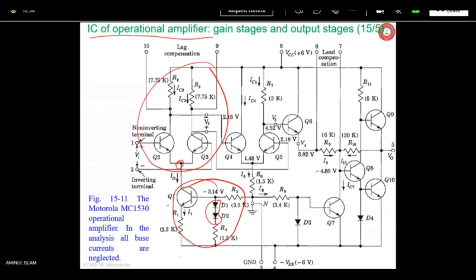Okay, so both are the same, I mean Q5 and Q4, so both VEN4 and VEN5 will be the same, and hence the current I6 flowing through this resistor R6 is the potential difference between this point and this point divided by R6, which gives you 0.986 milliampere.